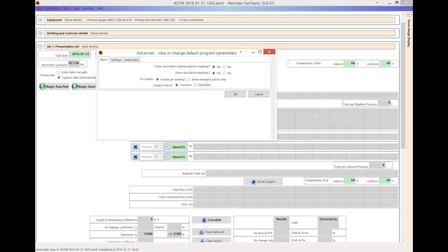And at the bottom, I have some illustrations here and a few that will talk about gauge control versus common or individual. So when things are set for common, they actually will be using the primary gauge as a scenario, and other gauges will be working off of that same fan speed to make it simple. Or I do individual, which means that they are all working as individual gauges with individual fans, and sometimes they can actually challenge each other.